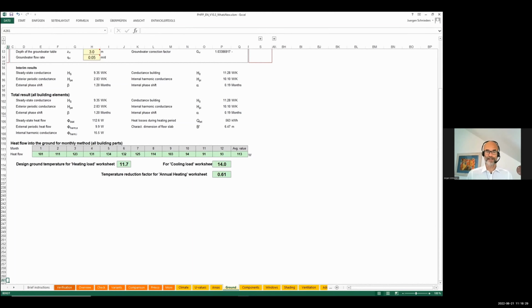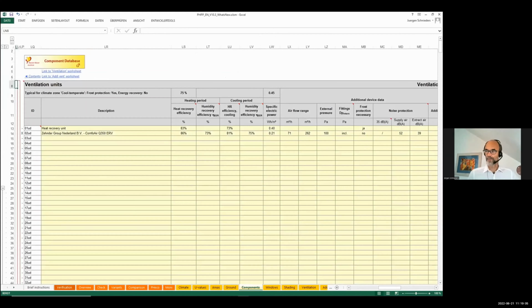The changes in cold climates, for example, in Germany, are on the order of 0.1, 0.2 kilowatt hours per square meter per year, so near zero. But in Southern Australia, it may make a difference. Also note that as a physical fact, higher summer temperatures would store more energy in the ground, so that the heating demand will then be reduced, not to a large extent, but there's some interaction that is now reflected also in the calculations.